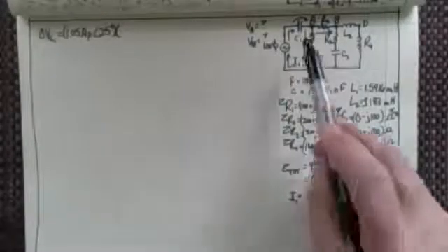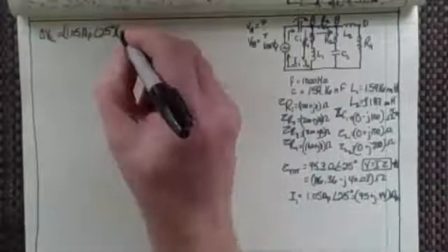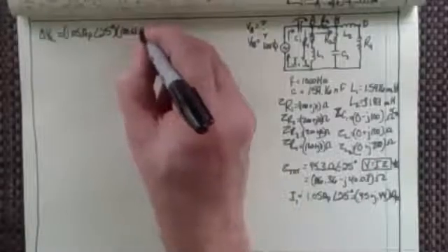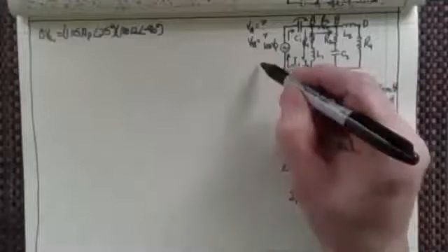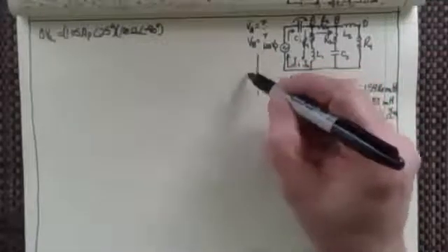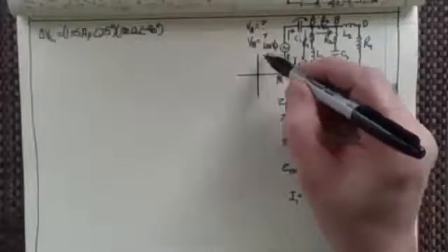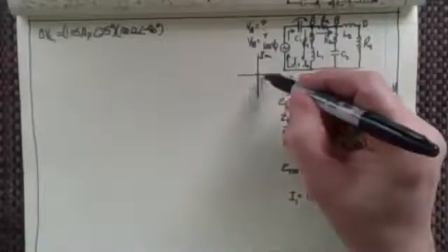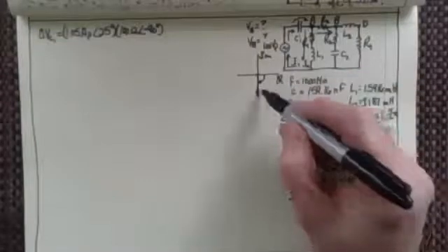And the impedance of the capacitor is 0 minus j100. Well, if I wanted to write that in phasor form, I could say it's 100 ohms at an angle of minus 90 degrees, because minus j is the minus j direction on my complex plane, and let's not forget the complex plane, right? My real numbers and my imaginary numbers, because minus 90 degrees is going to be down here, right? And isn't that where you've got it?